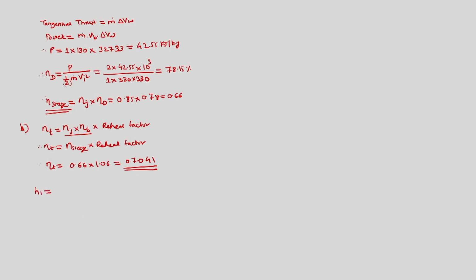We can find out the enthalpy at the inlet to the nozzle from the given temperature and pressure condition, and that is equal to 2902.3 kilojoule per kg.